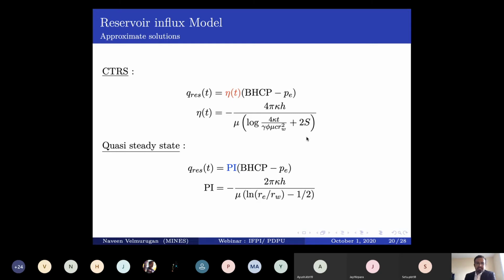And we can consider it as zero during real-time operation, when you want to model real-time drilling operations, because when you just drill your wellbore, the formation is very fresh, and it will not affect your skin factor at all. With prolonged production, or if you stop your drilling activity for a very long time, then you will slowly have a buildup of mud cake, in which case you might have some additional skin factor.